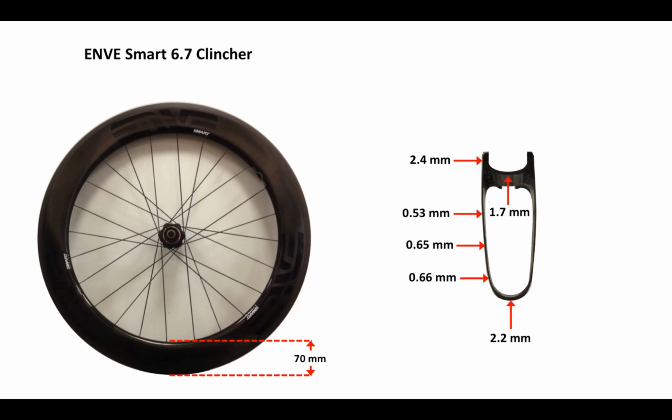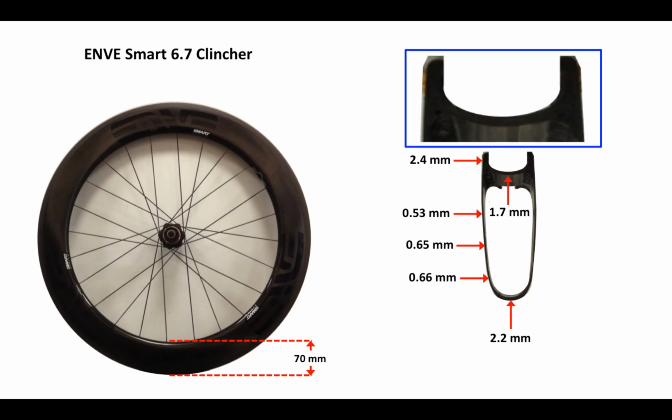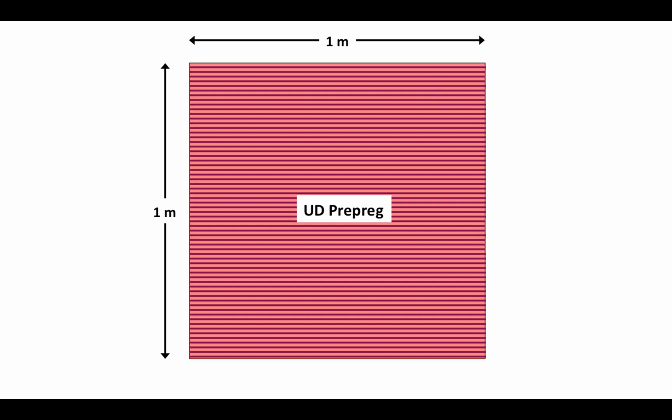This is obviously a clincher rim, and this part of the rim has to be pretty sturdy because when I put a tire on and then inflate it, there is quite a bit of sideward force on the rim. If we expand that part of the rim, we see this picture, and that side force from the air pressure creates a turning moment and tries to bend the rim out. That, of course, is not unique to carbon. Aluminum rims tend to do the same thing.